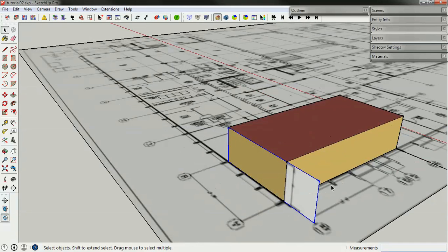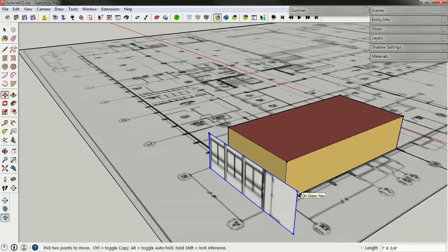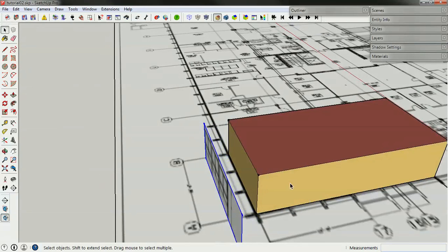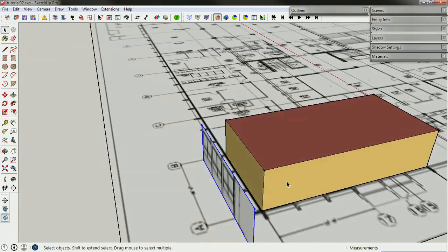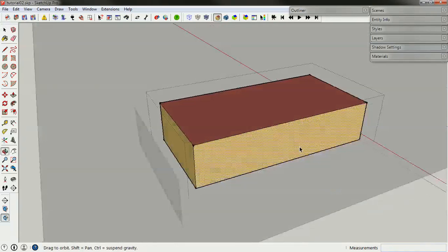And now I want to add openings to the box. One thing that's important to note about openings is that they are considered children of a parent surface. So the way that EnergyPlus finds the openings in the wall and knows the orientation is by locating first the wall itself, and then locating what is a child of that surface.